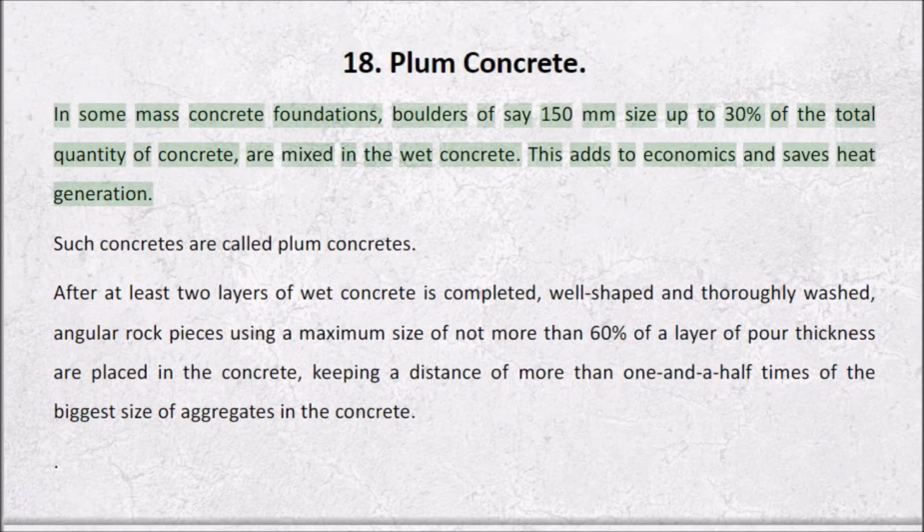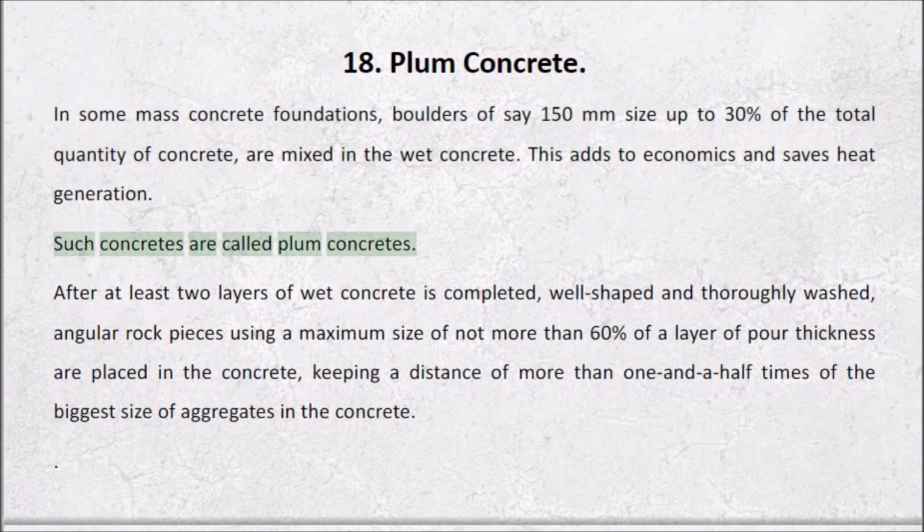In some mass concrete foundations, boulders of say 150 mm size, up to 30% of the total quantity of concrete, are mixed in the wet concrete. This adds to economics and saves heat generation. Such concretes are called plum concretes.